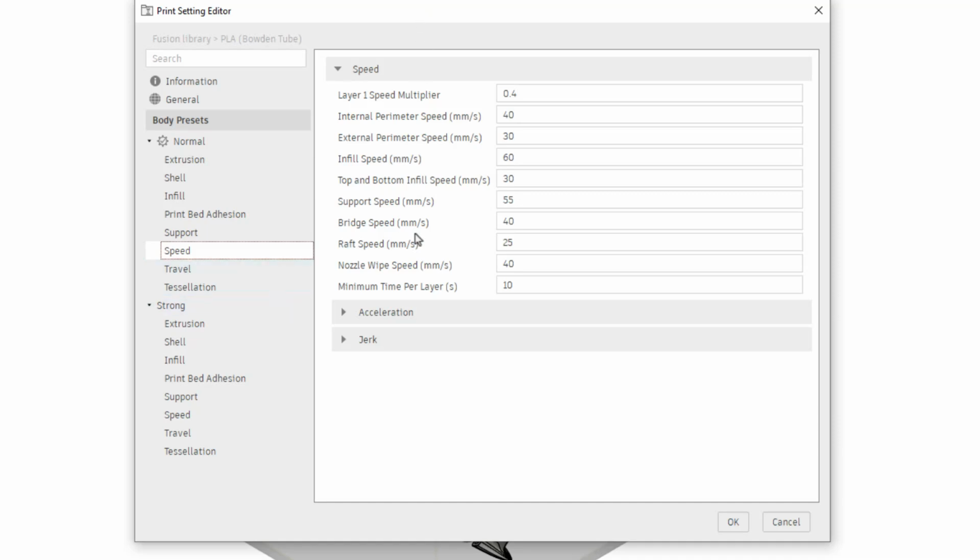So this is where we really need to convert the settings from a default slicer for your printer into information that works for you. So what I found is I was able to get decent prints out of the Fusion slicer. I just didn't have the luxury of having those preloaded values from the manufacturer that I could tweak up or down based on how the print was going. You really are starting more from scratch.